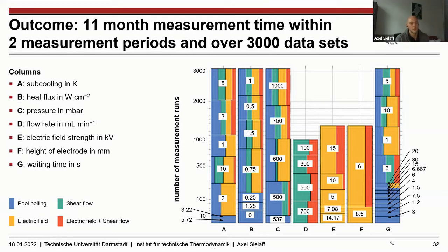You mentioned press fitting, but this particular sample in the Ruby was also press fitted, and the air gap was not prevented by any other glue or something between the section and the heater. Correct. The crystal was fit quite tightly into a holder. It was a plastic holder. So this was especially not caused by the leakage requirement, but by the alignment. Because the requirement, I think, some years ago, was 300 micrometers from the center of the electrode to the cavity within the crystal. And you have to go the whole way around from the cavity to the holder of the heater, down the basement of the equipment to the electrode, then to the center of the electrode, and have a misalignment of 300 microns, as the geometrical fittings had been quite tight.